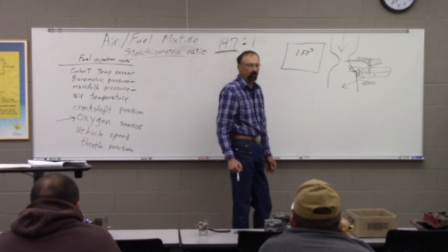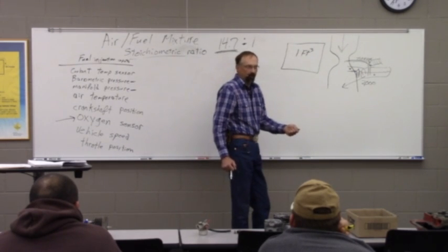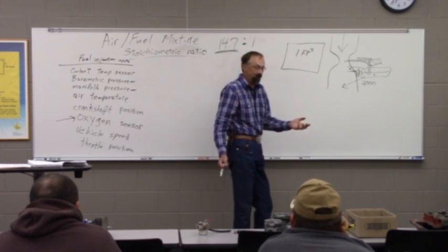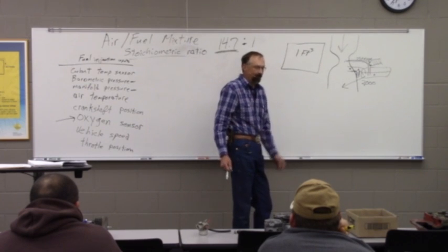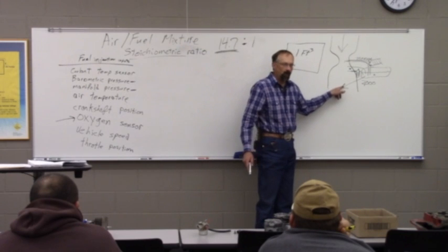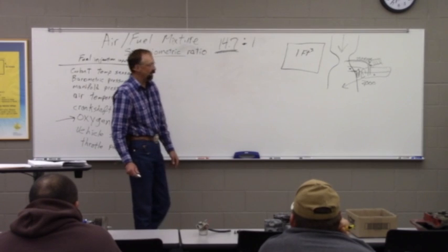Usually you didn't wind up needing to do that much if you had a manual choke and you had kind of figured out how you needed to make it work on this particular vehicle. But the ones with the automatic chokes that maybe were sticking a little bit, pumping it a little bit and giving a little squirt of that right straight into the airflow really helped.